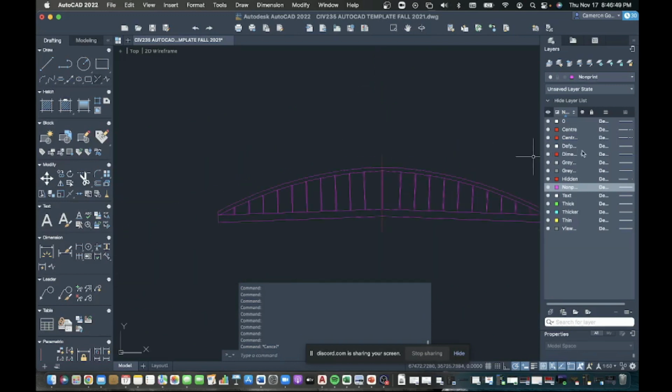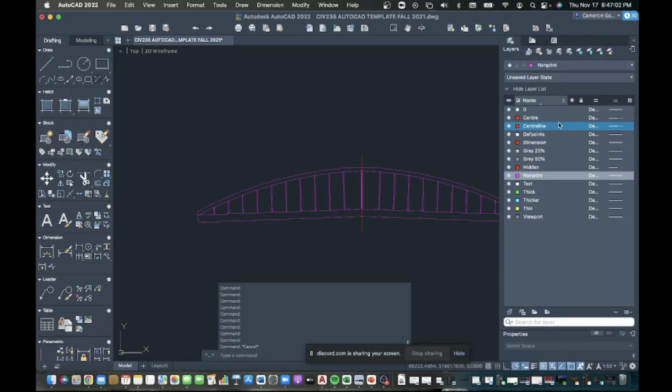And what this allows me to do is turn on and off the visibility of this. So I can go to center line here. I'm just going to make this bigger so you can see the whole name. And this is my visibility. I can hide it or show it. Right now it's showing. It also may look like a light bulb on Windows. But you can click on that, and as you can see, it's deselected now, and the center line is gone. But if I select that again, then I'm showing my center line. So that's how you turn on and off a layer and create a layer.